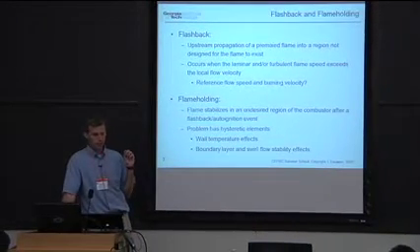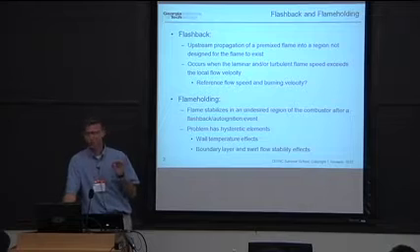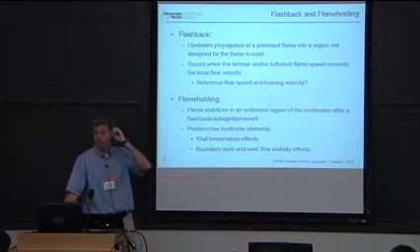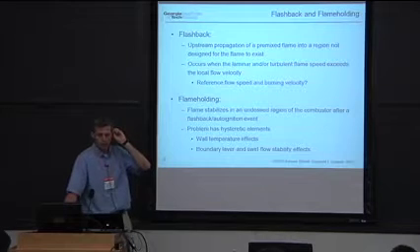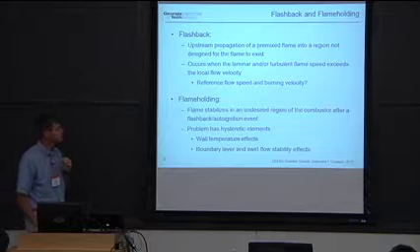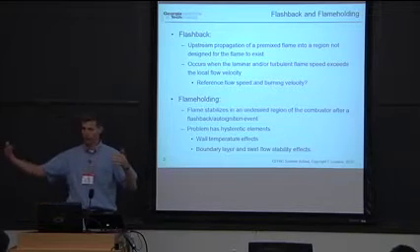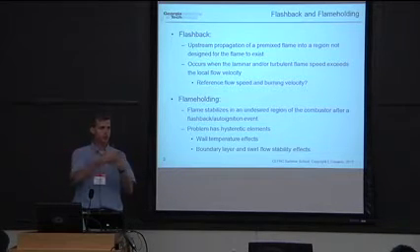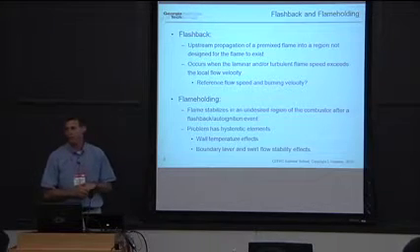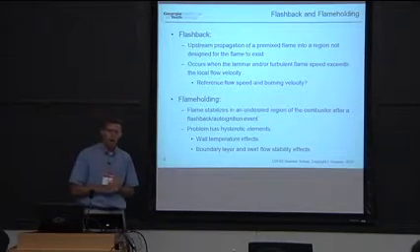Flashback is one of the key mechanisms for major, massive part failures in gas turbines. It occurs when the laminar and/or the turbulent flame speed exceeds the local flow velocity. So the fish can swim upstream. The flame can swim against the stream and propagate upstream.